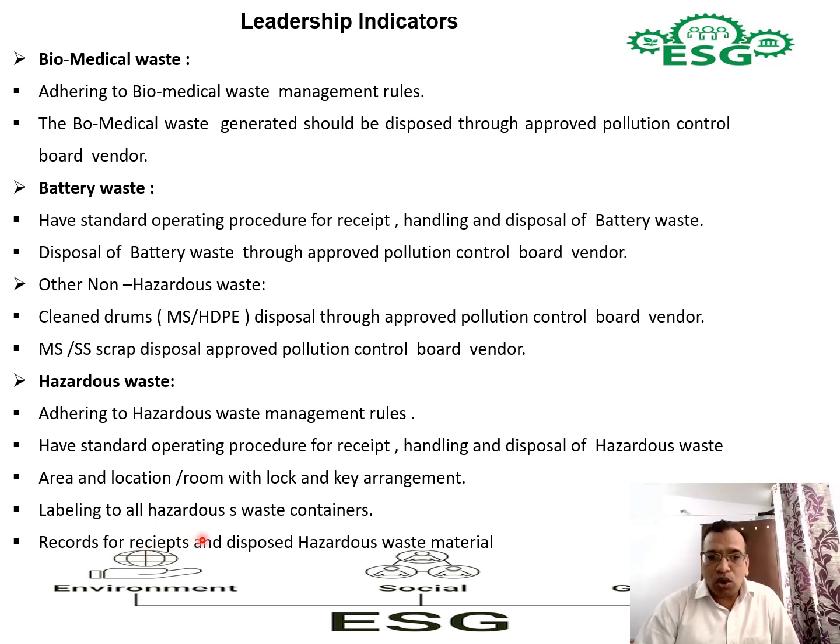Then labeling of all hazardous waste containers. Whatever waste has been accumulated in the dedicated room, all the waste should have a label as per the hazardous waste management handling rules. Then records for receipt and disposal of hazardous waste material. The pollution control board has given particular formats, so in that format you have to keep the records of all the hazardous waste.